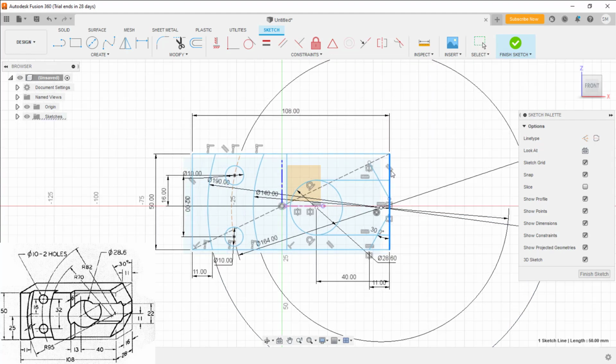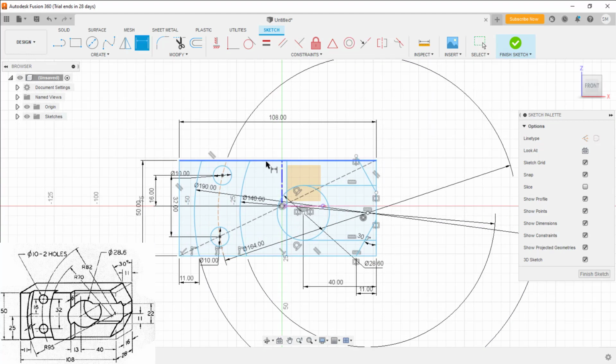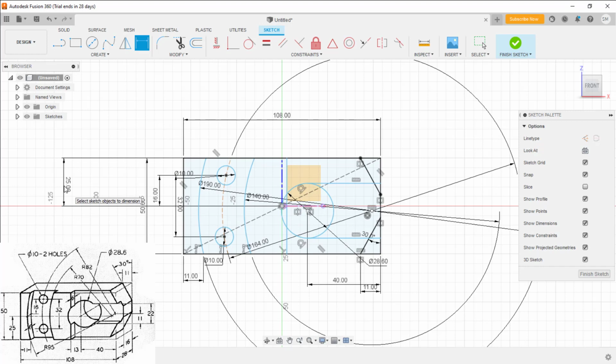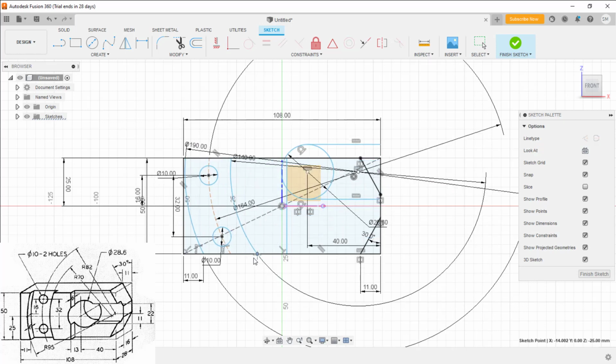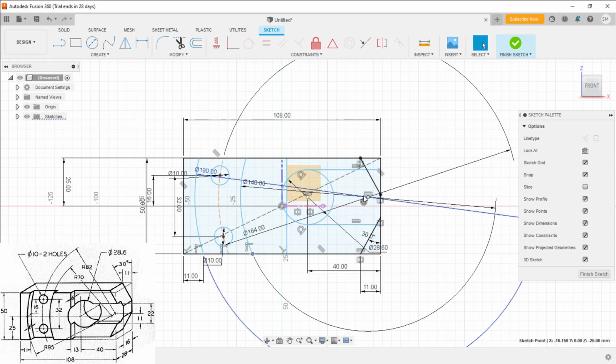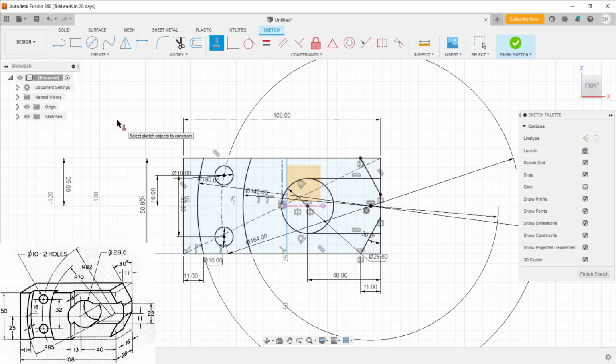This entire sketch is underdefined now. So here I'll define the vertical and the horizontal dimensions. So this is 25, half of that, and you could say it is okay now. You can even move this. Yeah. Now this and origin horizontal. It is fully defined, right?